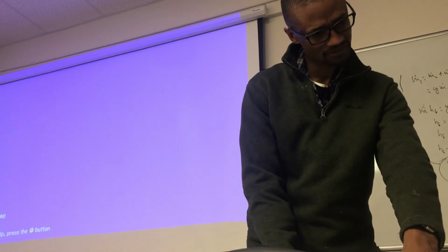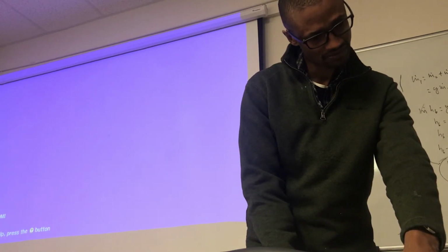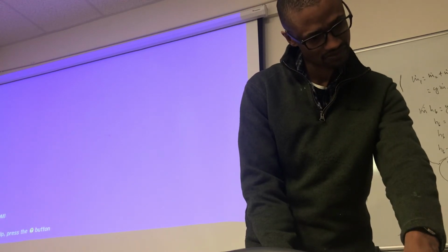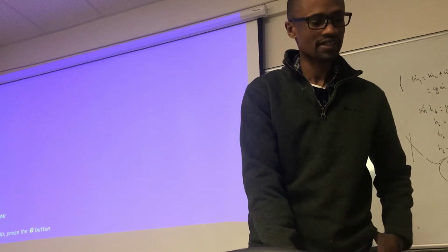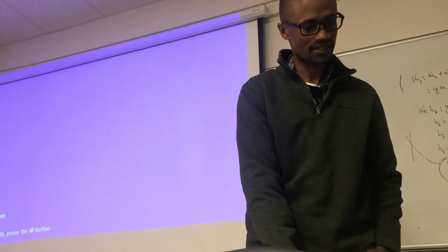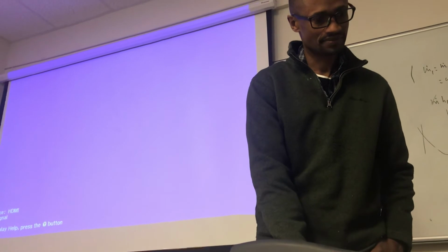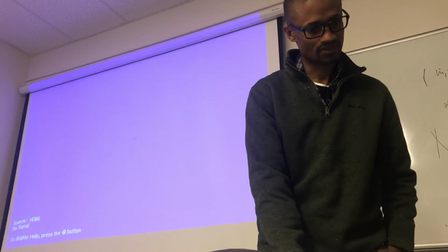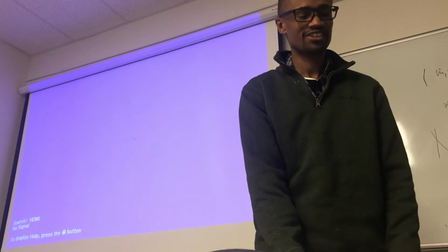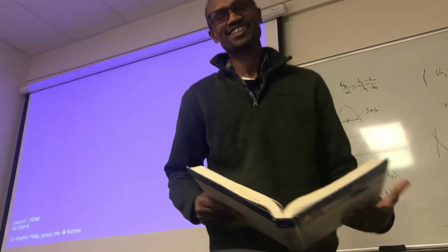I would use perhaps H2 is equal to H1 plus X times HG minus HF. That's usually the way we write them. One would say H is equal to HF plus X times HG minus HF. Some people call this HFG. So it's the same thing. Exactly the same. Gotcha. Yeah. All right?